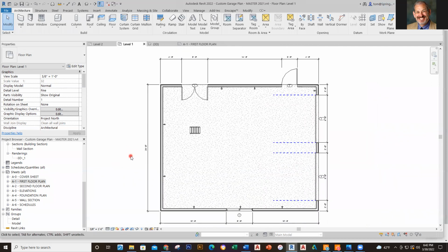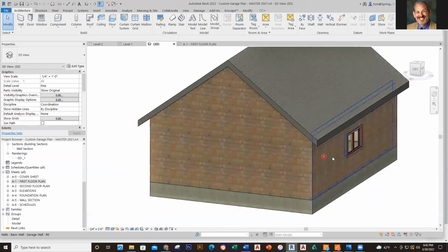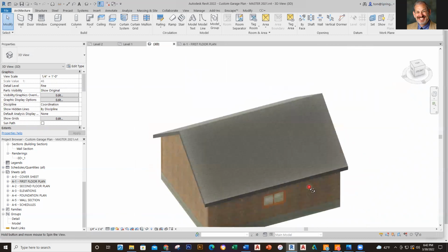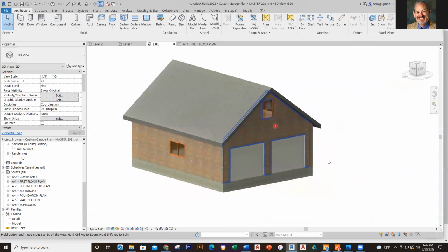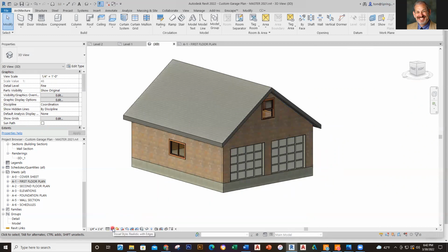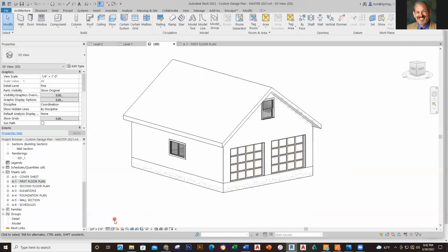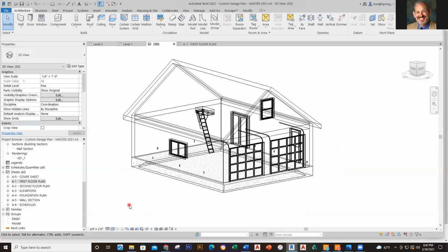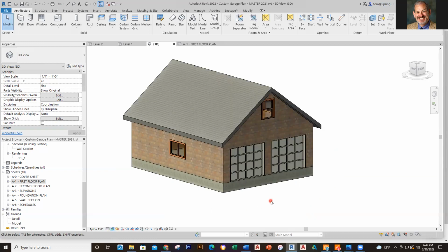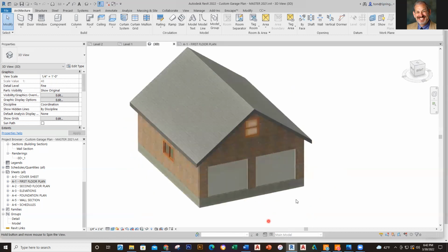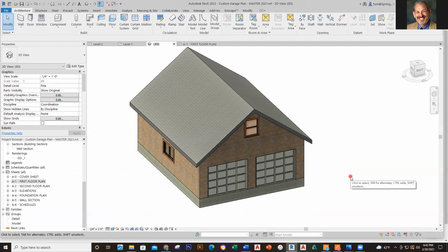And these same views actually go ahead and work here too. If I go to 3D and go to here, I can go ahead and take this and rotate this around like we talked about before. And once I rotate that around, I can change the view down here by clicking here and changing this and making consistent colors like that, which looks like that. Or I can go up here and go to hidden line like that. Or I can go here and change it to a wireframe, which you see right through it, which is interesting, but a little bit spooky. And then I go down here, I'm going to just use realistic because that works pretty darn well for this right here. Okay, so these are things you got going on right here when you start working with Revit.